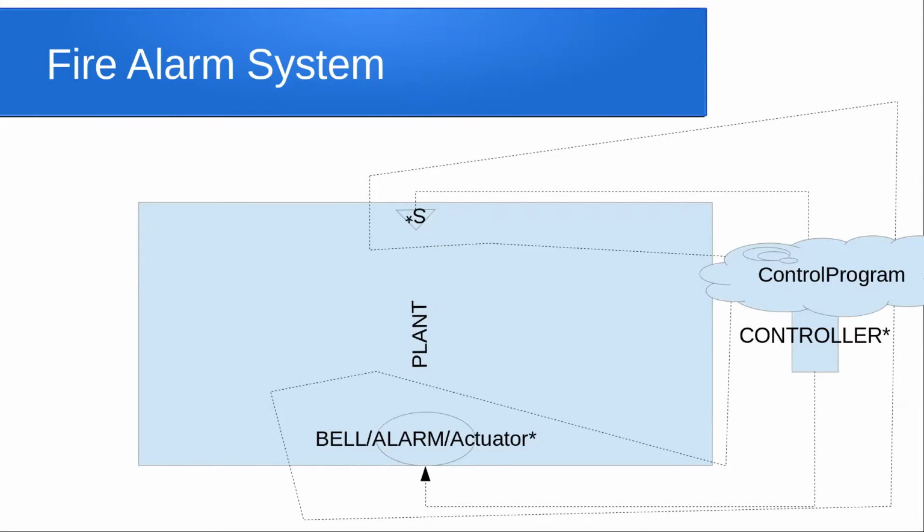So we use a network of sensors spread across the entire floor area that always keep track of how much LPG has leaked into the air, so that if it is beyond a certain threshold, the control program in the controller triggers an alarm. So whenever a certain volume of LPG gas is identified beyond a certain threshold, the alarm starts ringing, right?